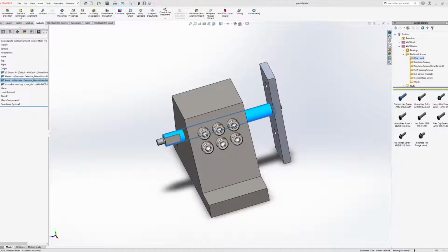Oh, well, that's because it's the guide. So that actually also matters, I believe. Okay, I forgot about that. So certain things, if you're in your mass properties menu, it will define different parts. So you can find the center of mass of just a specific part. So you want to make sure that this top thing in the box up here is going to be your assembly as opposed to just a specific part. That might be why it was happening.